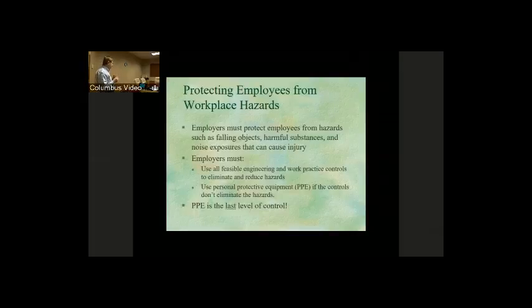But personal protective equipment, again, is only the third option. The first two options are key. One, engineering controls, that means proper ventilation and vacuuming. Secondly, would be administrative controls, reducing the amount of time an employee may be exposed to a particular hazard, job rotation of employees where necessary. And after those, only after those three, personal protective equipment. That is the last line of defense.